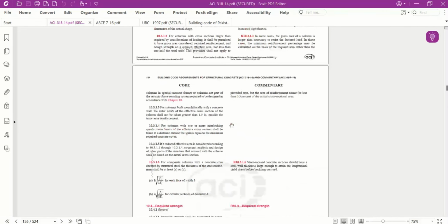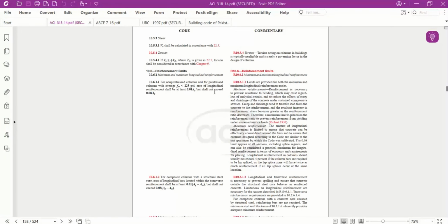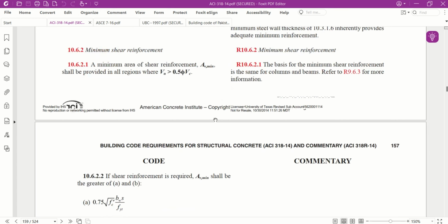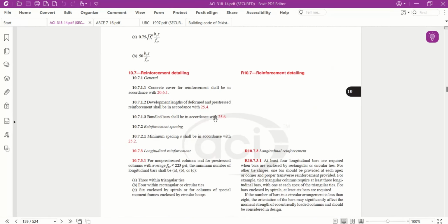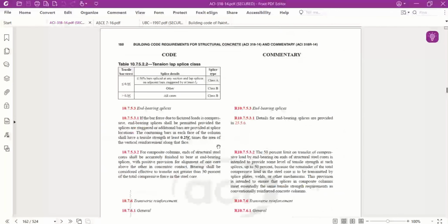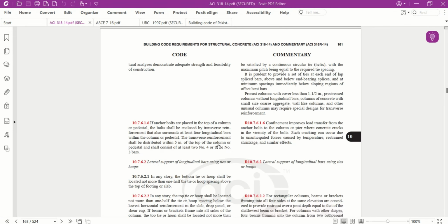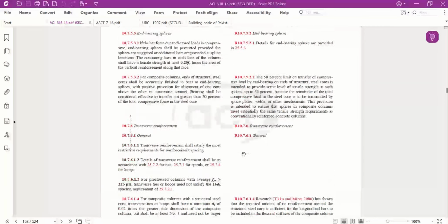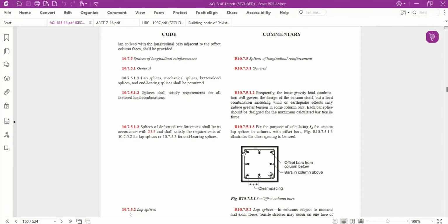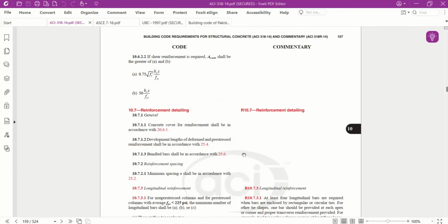And if I go through the minimum criteria, for example, these are the different requirements for the minimum shear reinforcement in the columns that you must provide if you have less reinforcement in your finite element model. So there is a section in which they have given the minimum reinforcement ratio. I have included it in our lectures, but I wanted to go through this quickly.